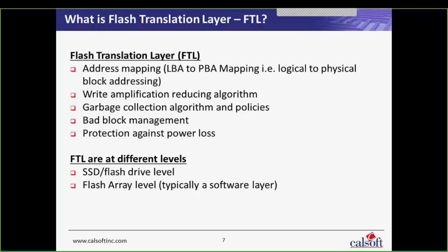Normally, a flash vendor implements a write amplification reducing algorithm, which I have already covered in the previous slides. So there has to be a write amplification reducing algorithm to have better write performance. There has to be a wear leveling engine written on the FTL to have better wear leveling addressed. We'll talk about wear leveling in future slides. Then there is a garbage collection algorithm and policies, which normally a flash vendor writes into their own FTL layer.